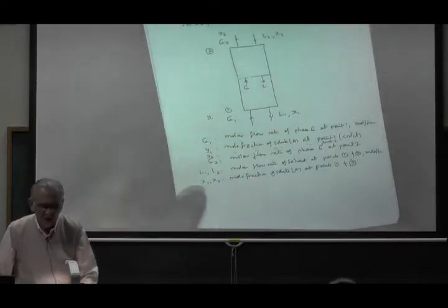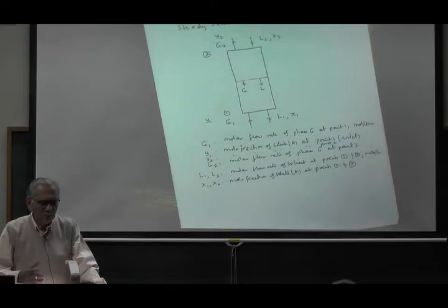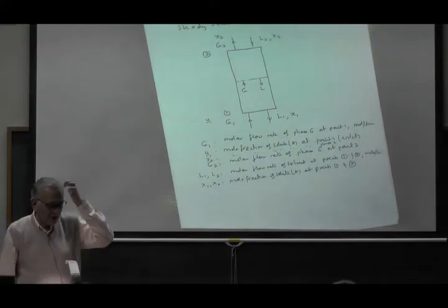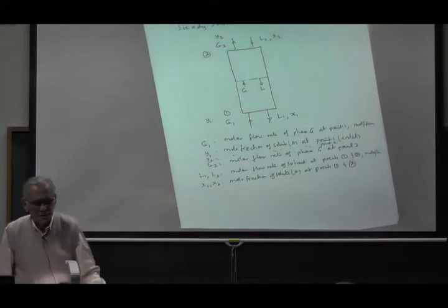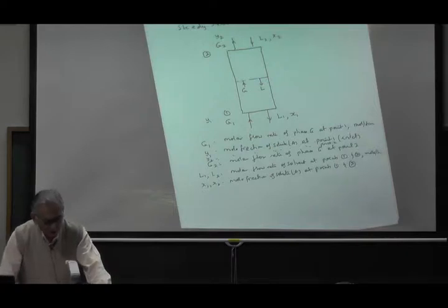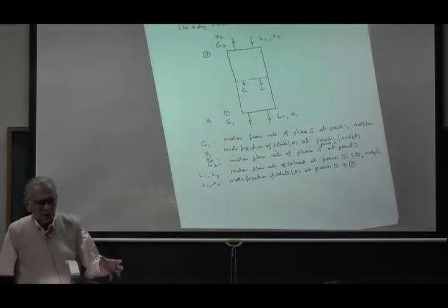And similarly, G is the flow rate of the gas, which includes the solute plus the non-solute part. Now, is G changing along the height? Yes. What about L? Also changing. So that becomes a problem, because G and L are changing, but the solute free part is not changing.